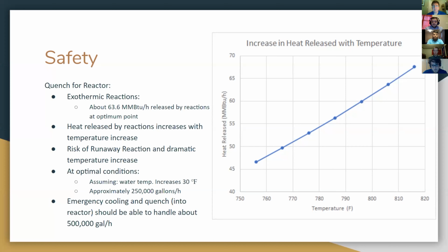Some of the controls that they'll use involve hydrogen. When you start having issues like that, you're going to want to cut back on that, because that's what's allowing this reaction to occur. It's one of the main elements. Also, cutting back on your heaters is another really good decision on this. You don't want to hold liquid inside one of these hydrocrackers. You want to keep flushing it through with cold oil and everything. It's just a couple things to look into when working on any projects like this.